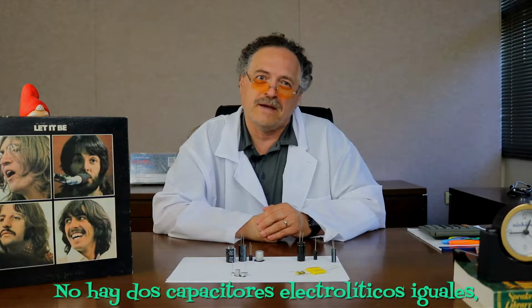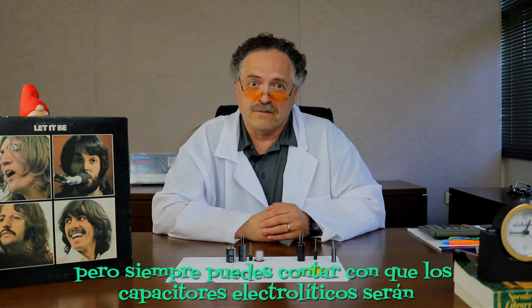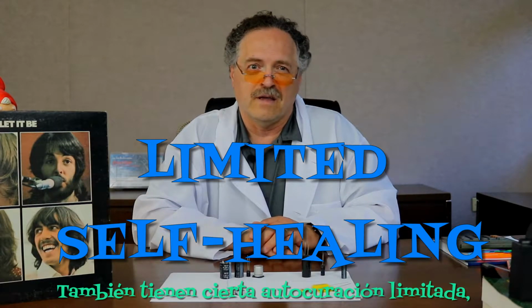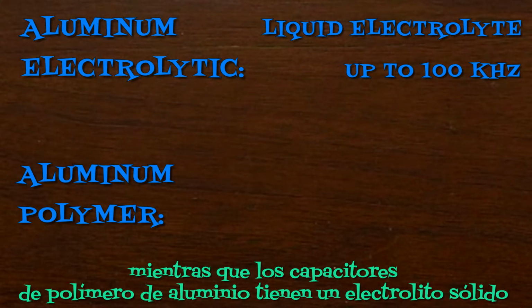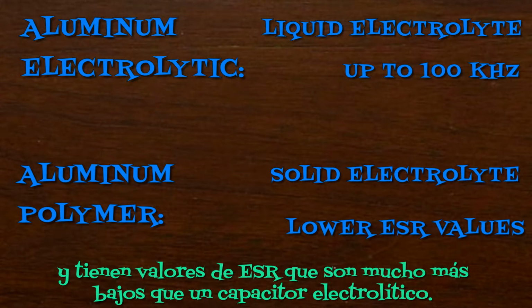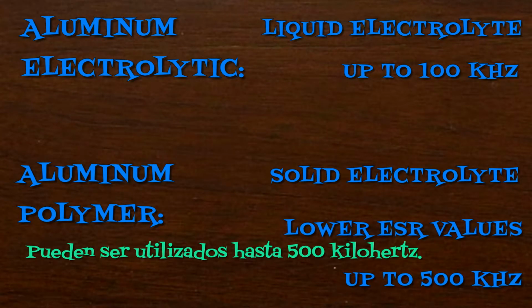No two electrolytic capacitors are alike, especially if they contain different electrolytes. But you can always count on electrolytic caps to be polarized, very small, and inexpensive. They also have limited self-healing because every superhero has its limitations. Example time. Aluminum electrolytic capacitors have a liquid electrolyte and can be used up to 100 kilohertz, while aluminum polymer capacitors have a solid electrolyte and ESR values that are much lower than electrolytic capacitors. They can also be used up to frequencies of 500 kilohertz.